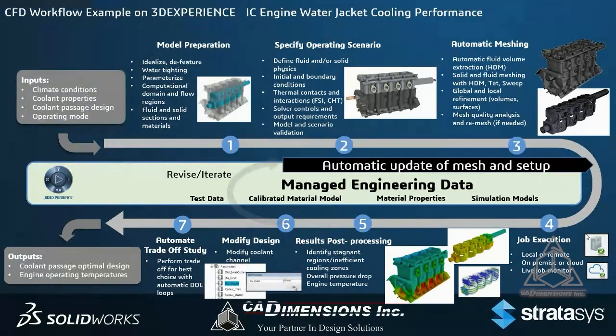And then we ultimately come to our outputs, right? We get either the optimal design of the coolant channel if we have to do a little bit of rework. We could take a look at the engine operating temperatures just so we know what they are, right? Depending on what we're looking for, whether it be flow rates, pressure drop, we ultimately arrive at the answer that we are looking for.